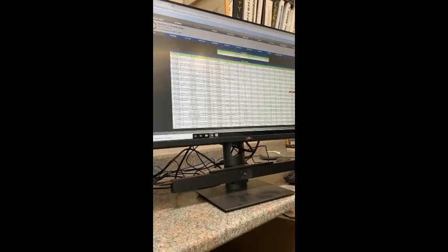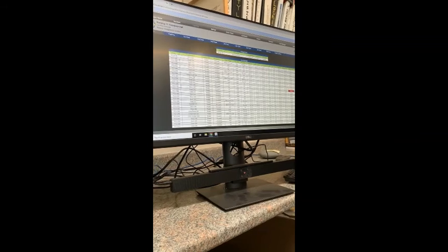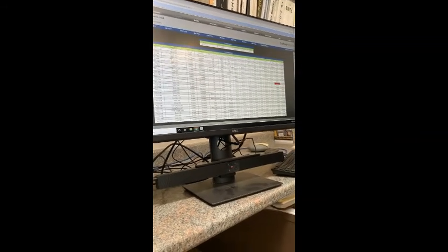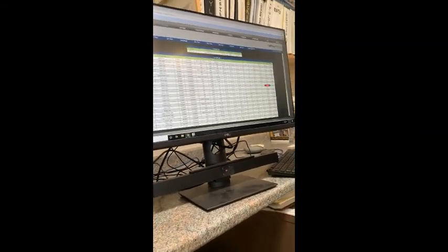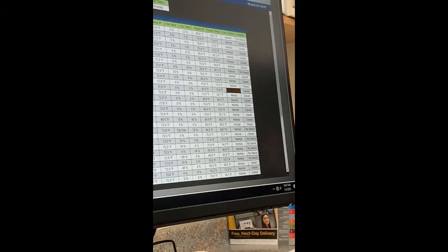So the common areas, you'll see that they don't have room sensors or window sensors because those windows don't open. The other ones, you'll see that they're closed. You can override it closed in case a window sensor goes faulty, so that they're not without heat or without cooling.